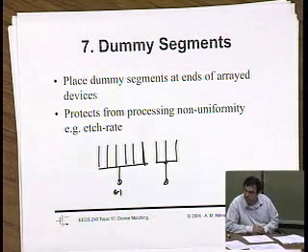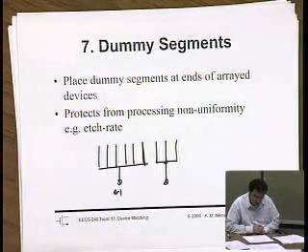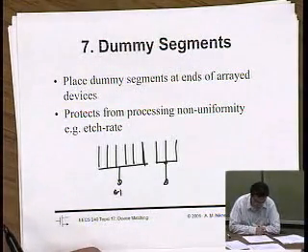The dummies, well, the fingers on the left and the right are going to be thinner because more etchant is consumed in the middle than on the sides, and therefore the etch rate for the ones on the sides will be much faster. And in this case, the 6 on the left and the 3 on the right will not match. Okay, very good. Yeah, exactly.